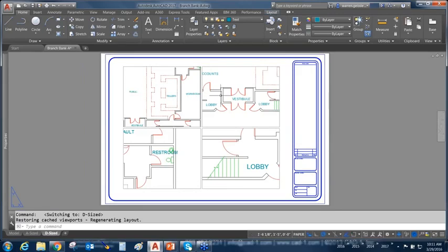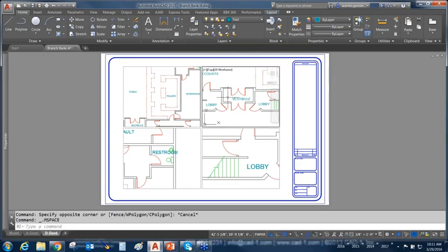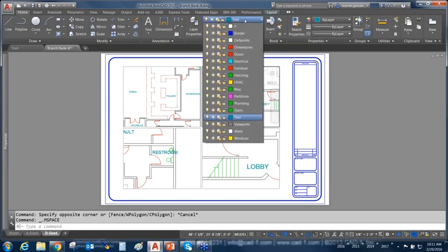Well, when I came over to other scale viewports, what do I do? Historically, what we would do is we would copy that piece of text, put it on a separate layer, scale the piece of text for the new viewport, and then on a viewport by viewport basis, I would have to come up to my layers and use that other icon over there to freeze and thaw different layers of text inside of different viewports. So effectively, I've got all of my annotation in one location. It's in model space, but I've still got multiple pieces of annotation and multiple sizes.